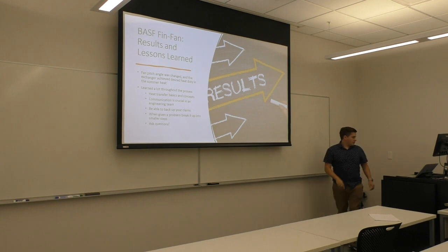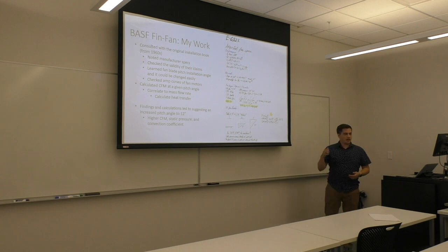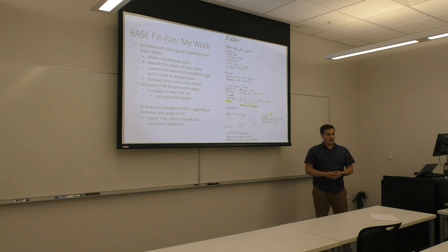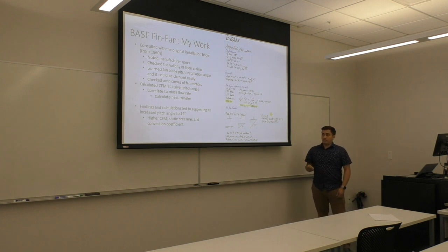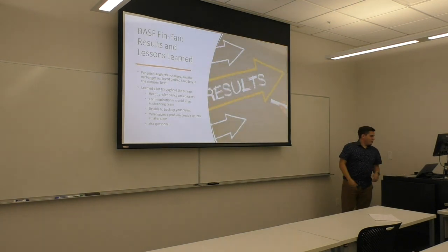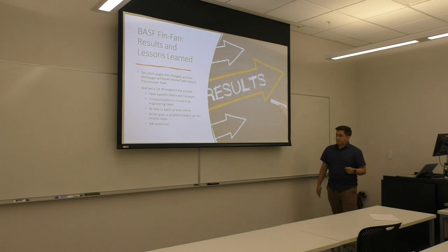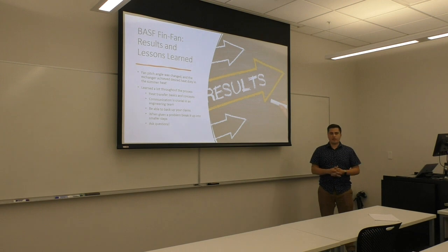Actually, I did skip over a really important point. As you increase the pitch of the fan blades, the motor actually has to work harder to push that air. So I had to make sure and verify that we were not going to burn out the motors the second that we did that. And we did find out that there was enough headroom inside of those motors so that wouldn't happen. After doing that, we were able to get it fixed, we got it changed up, and it did achieve the correct heat duty required to cool off that process.